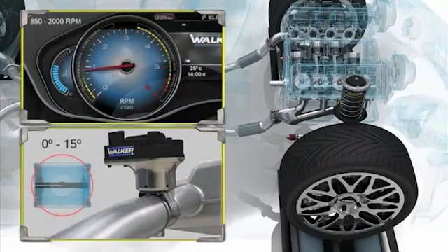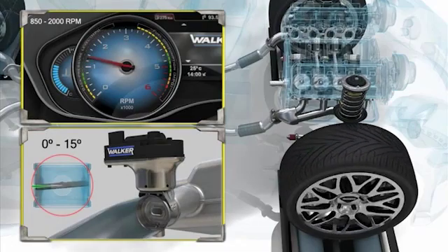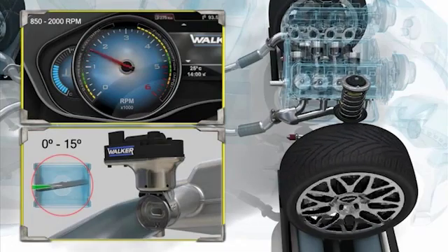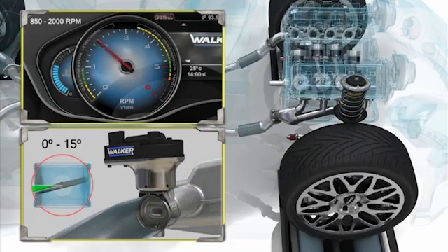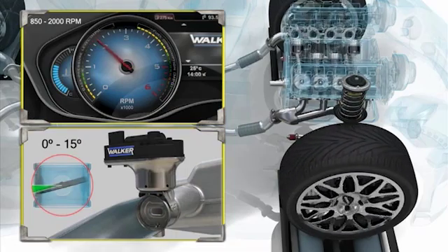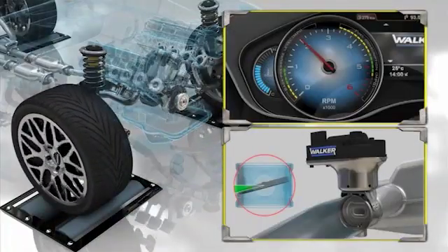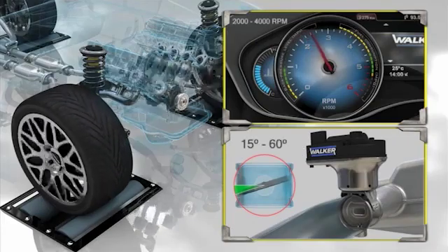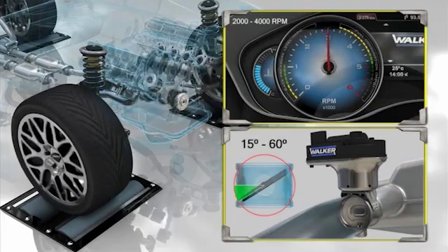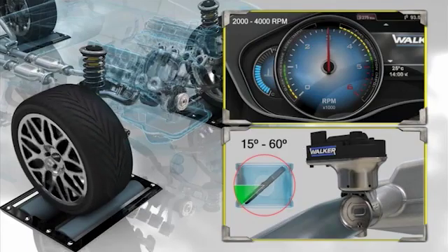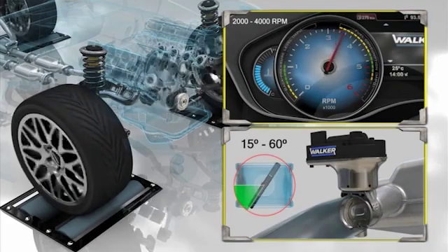At low engine speed, the valve will remain closed or almost closed to the flow of the exhaust gases, thereby increasing the back pressure values to optimum performance levels. When the vehicle is running, the valve opens or closes depending on the engine's operating conditions. The disconnection of cylinders, subsequent reconnection, increased speed, etc. will be the conditions which determine how much the valve opens.